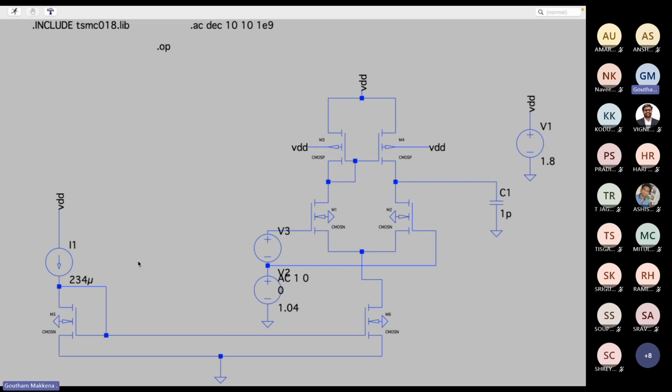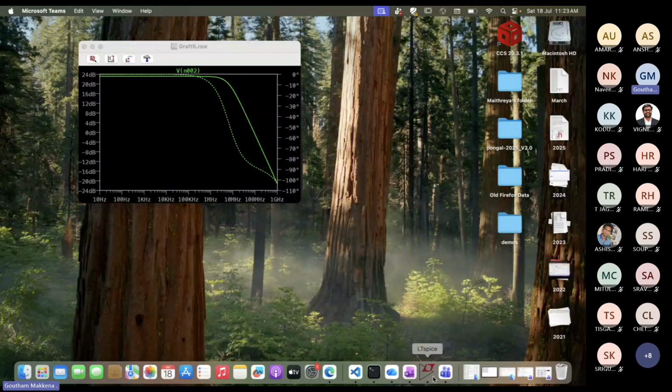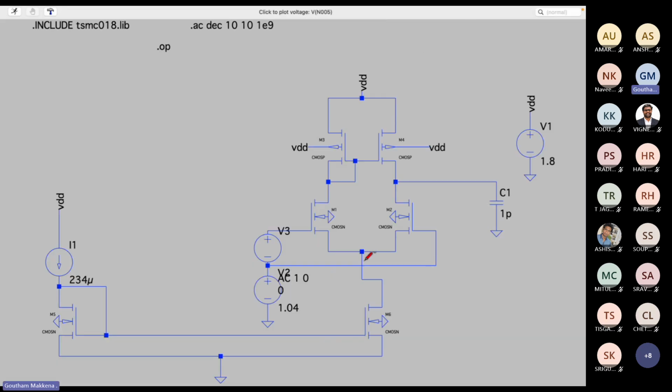We can have a better current mirror, right? Okay, so what is the better version of this current mirror? All I am saying is this current mirror is prone to the node voltage here. And if you want I reference to be equal to I out, what all should be equal?